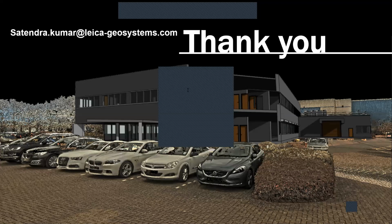And it will be accurate because the laser has a range to scan everything up to 500 meters or a kilometer. So even if you put your scanner on top of a building near the waterlogged area, around 100, 200, 300, 400 meters away, you can still get the data in laser and then do the analysis. So you need not go there. If it's a seaside or you have a container ship or a big vessel you want to scan, then you can bring the scanner directly onto the vessel and perform the scan there.